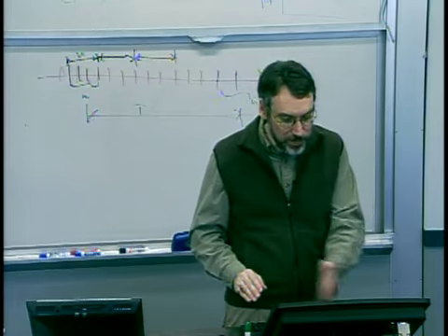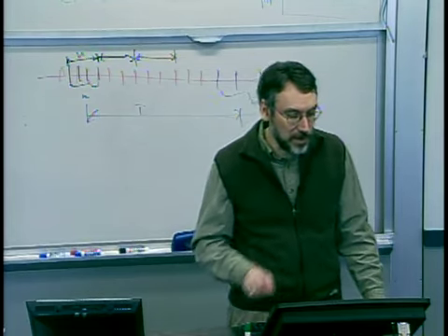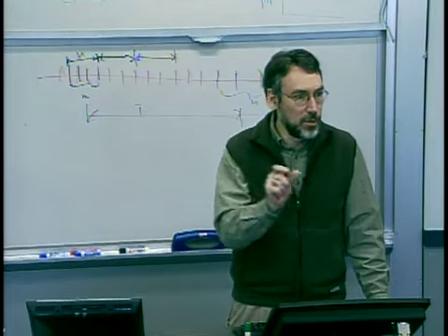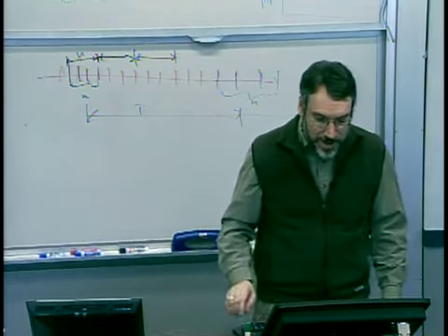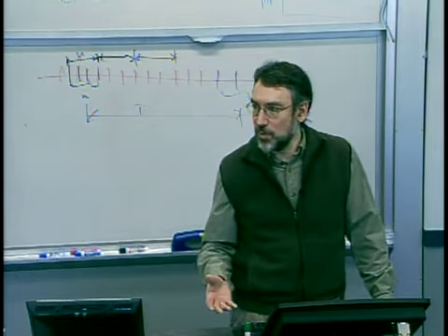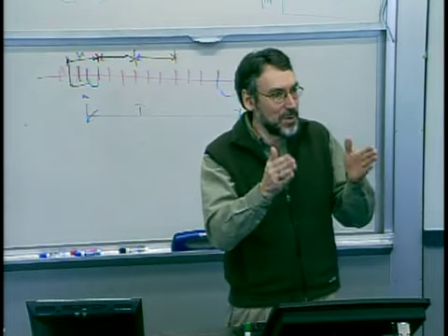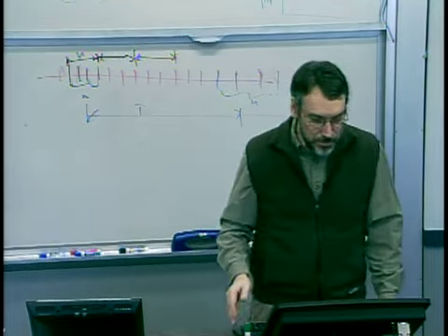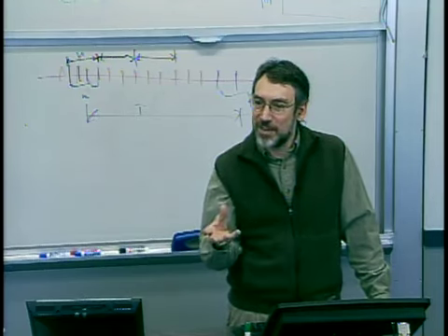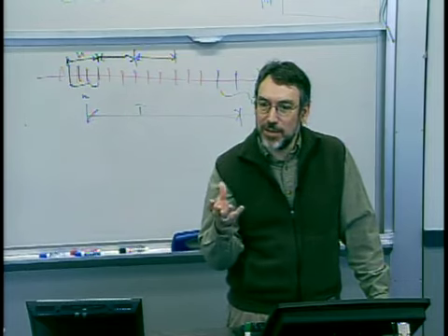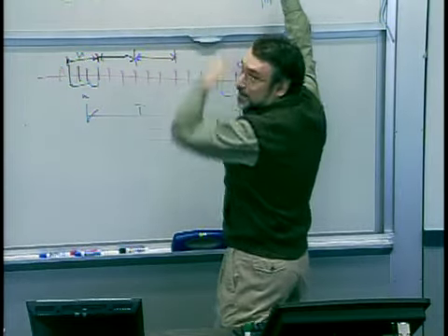So what I've got here is the run data, and then in the little purple pictures is an X-bar calculated for each group of 4 sample points. So every 4, I calculate the average, then I move on to the next 4 and calculate the average. And so in a typical X-bar chart with sample size n equals 4, where my sample time is also n equals 4, I've got a smoother curve here with the X-bar. And we didn't explicitly talk about it, but one of the advantages of the X-bar chart, what we talked about was the squeezing of the distribution down.